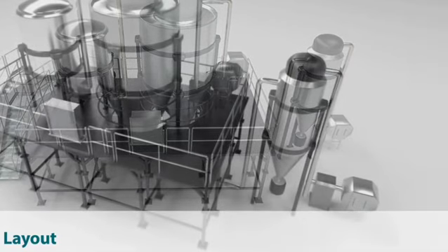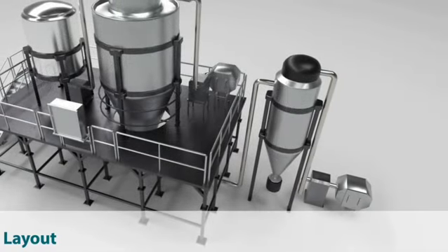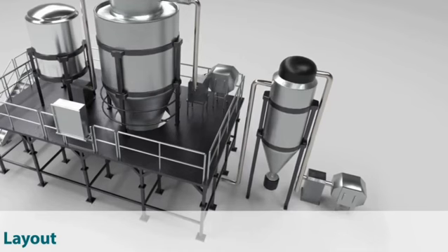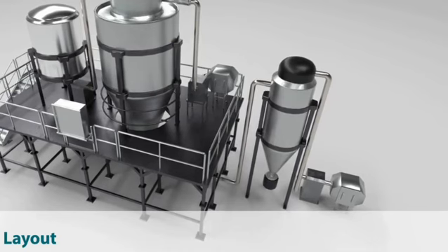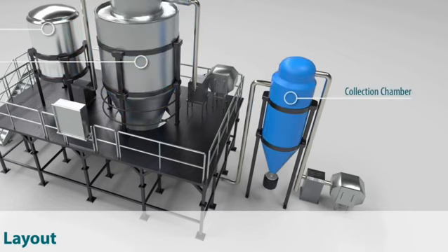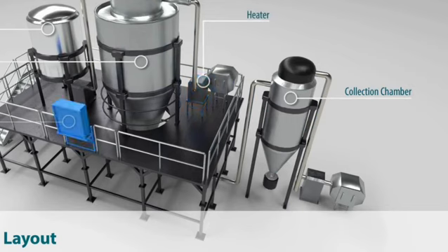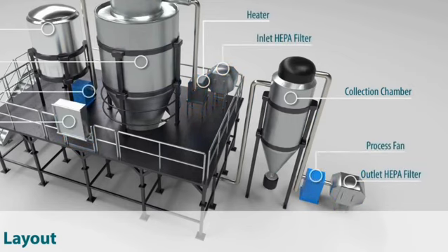After drying, the powder is separated from the air using a cyclone separator. The separator spins the air like a mini tornado, throwing the powder particles to the walls where they are collected in bins, while clean air exits the system. The collected powder is then cooled, sieved if necessary, and packaged in moisture-proof containers. This explains why milk powder and fruit powders pour so smoothly from packets without sticking.